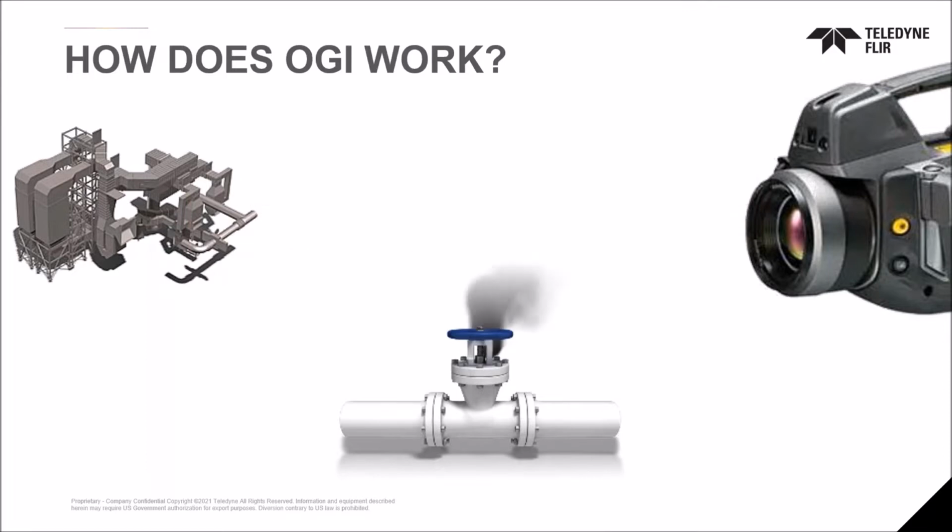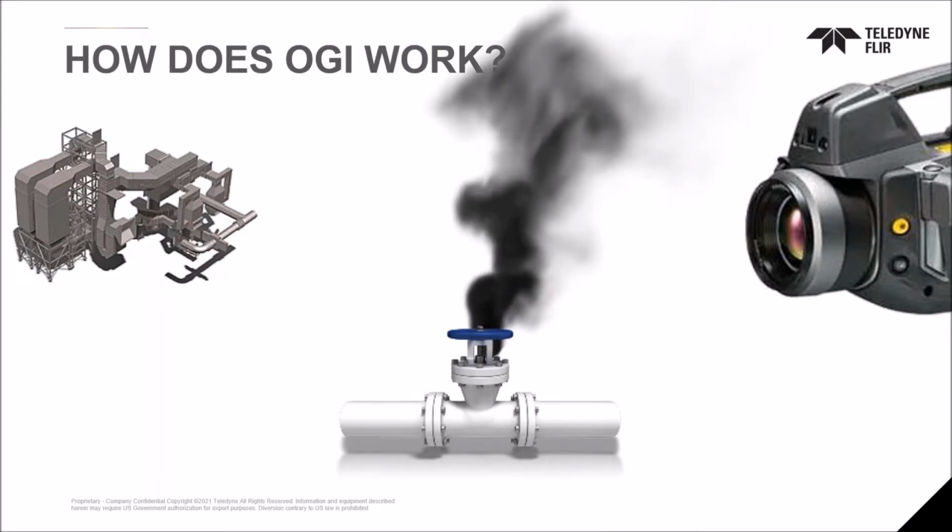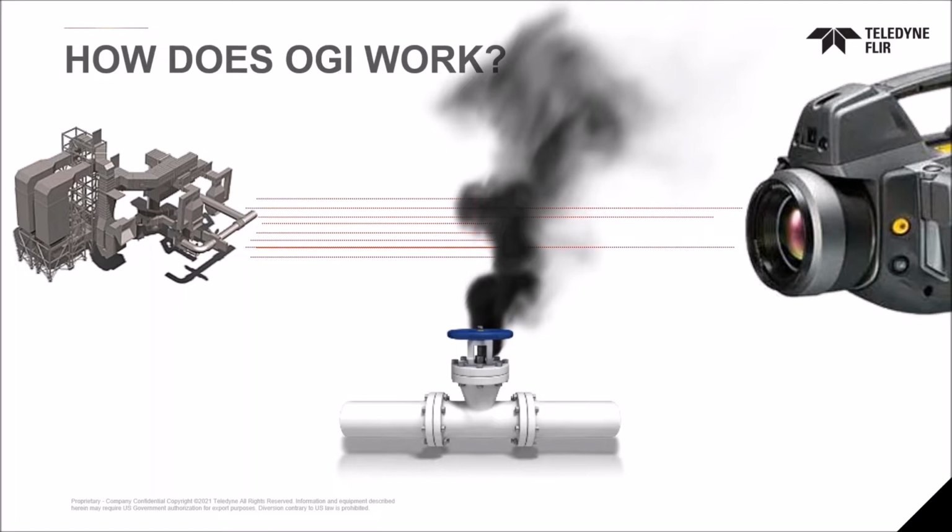At times, you may run into a scenario where there is a leak in between that background of energy you're looking at and the camera. What happens is that gas leak actually absorbs the energy before it can get to the camera.